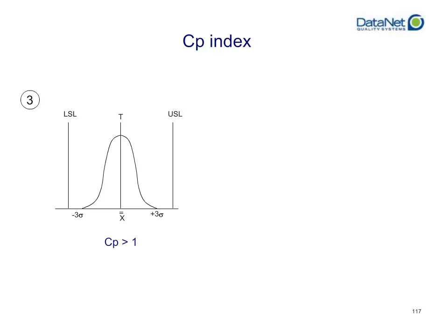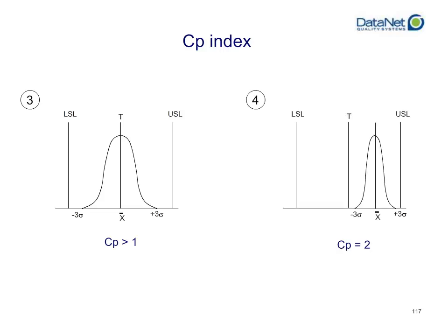In fact, if you want to quantify this, if your CP were to equal 2, that would mean that in theory, exactly twice as much of your data would fall within spec than it would if you had a CP of only 1. So you are twice as good, or you could theoretically produce half as much waste if your CP equaled 2 versus if your CP equaled 1.